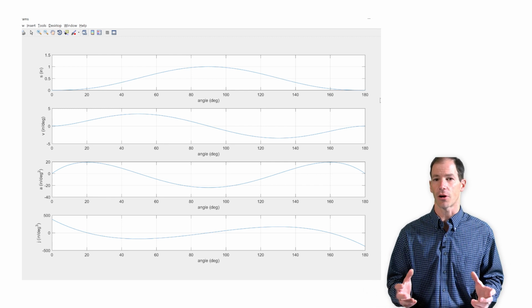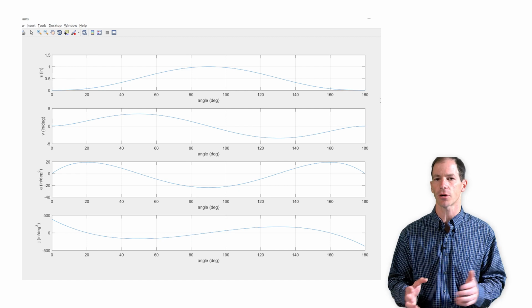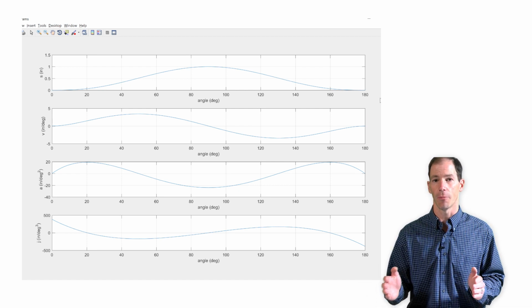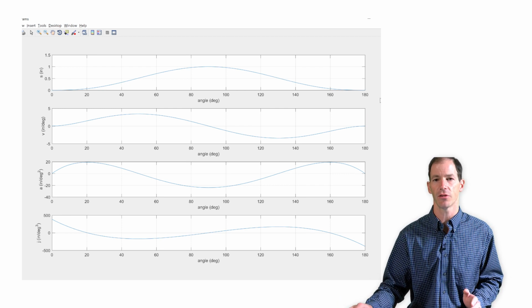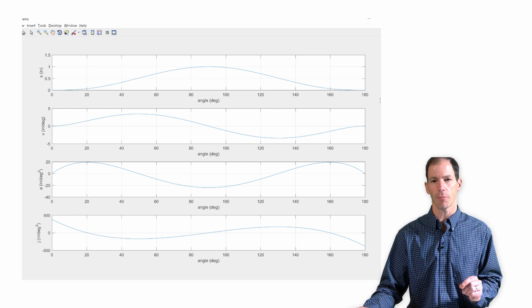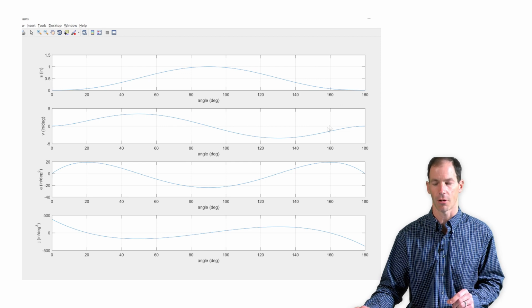So these polynomials are extremely powerful, and one thing that you're going to find is that when we start to do more complex cam design, we might have to break this up into more segments. So imagine that I could have this rise-fall segment as 2 different segments, and I could have the rise piece and then the fall piece. And the important thing between the pieces is that I match the boundary conditions through the acceleration.